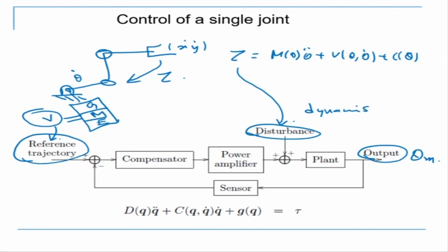So what does this basically mean? This means that if I'm trying to move in this direction, the dynamics will try and oppose that motion. Or suppose one joint is moving like that, and these two joints are not moving. Just because theta 1 dot and theta 1 double dot are there, these joints will be subjected to forces and moments. That is a disturbance on the controller, because the controller understands that the joint is not moving, it's holding the position at that angle, and yet it requires additional torque because this disturbance is coming from the first joint, which is disturbing the second and the third joints. That is the meaning of what this does.